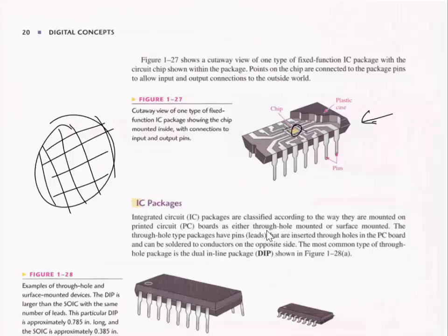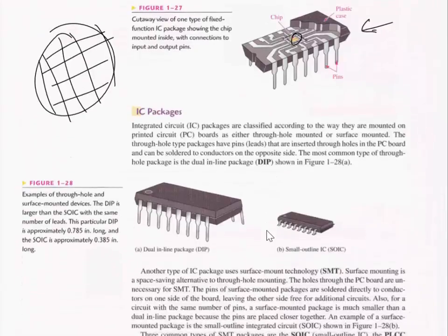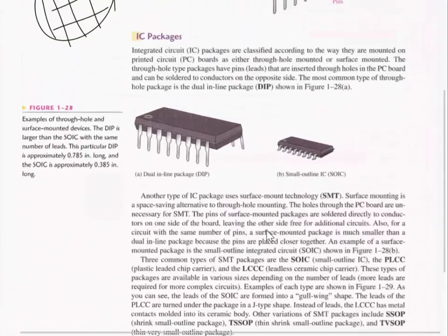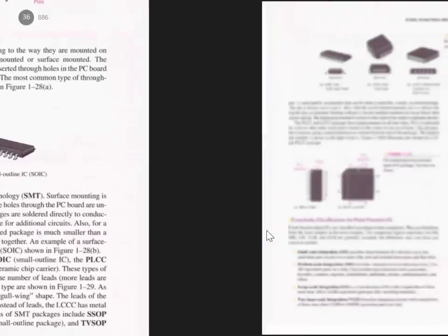Ceramic is common in situations where temperature is an issue. A lot of military and industrial electronics has to go into ceramic, especially if it's going to be operated in space. If you're talking about something that's going to go onto a satellite or a spacecraft, then quite often it will use ceramic. You'll see the most common package is the dual inline.